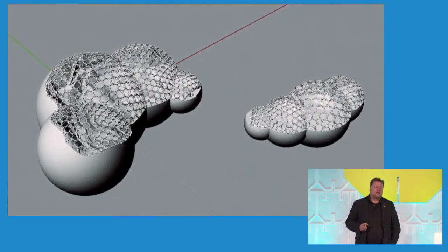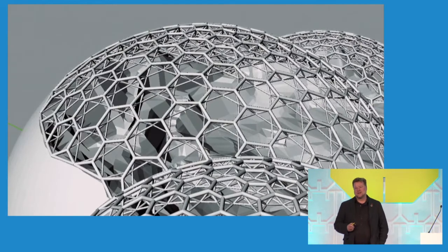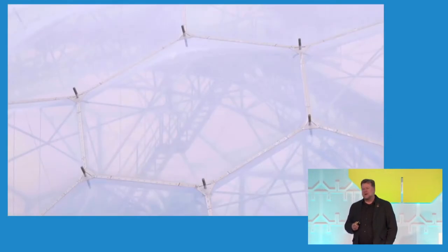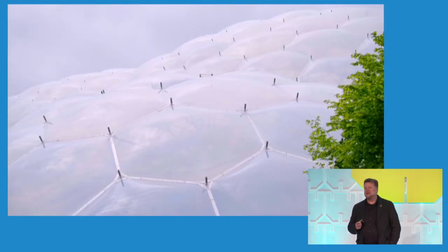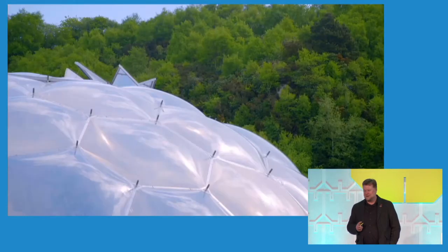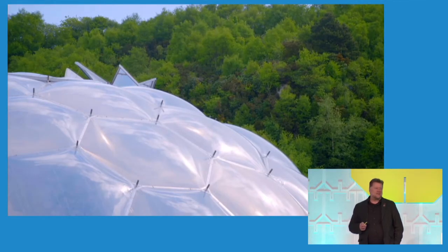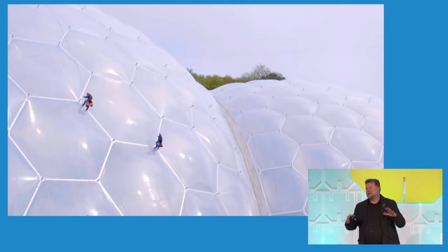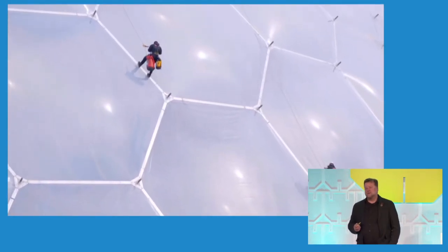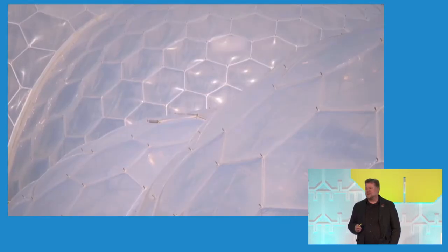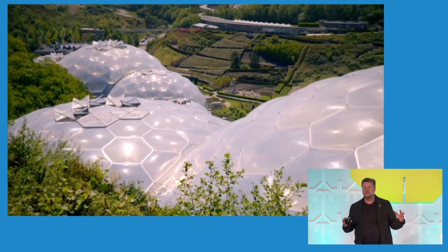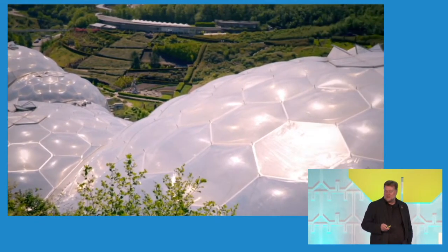So it meant we had a very lightweight, very efficient structure using the minimum of embodied energy. It uses around 1% of the energy you would have with a glass and steel building. So 1% of the volume. And each of those pillows spans around 11 meters without any structural intervention. So it meant that the actual weight of the roof, when we calculated it at 800 metric tons, was less than the weight of the air inside the buildings. So again, it's about ultimate efficiency.